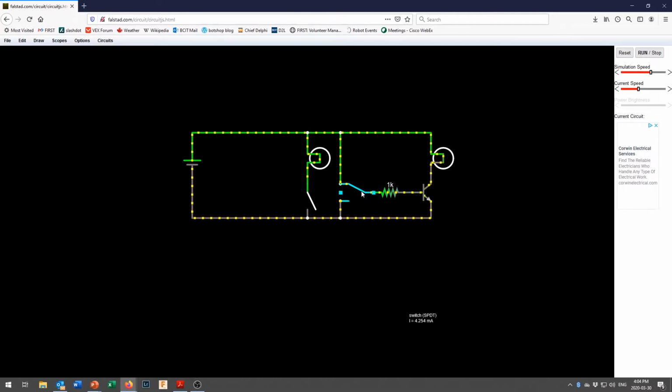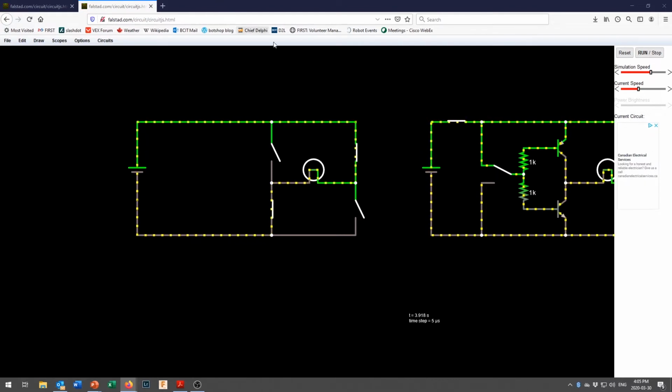And again, if you want speed control, now that's pretty easy to do because your Arduino can handle switching that on and off. And as you switch that on and off, depending on how much time you spend in the on position, your average voltage across the motor goes up, your average current through the motor goes up, and the average speed of your motor goes up. So you can get speed control with a single transistor, but you won't be able to get directional control. If you want directional control, you're going to have to get a few more transistors involved.